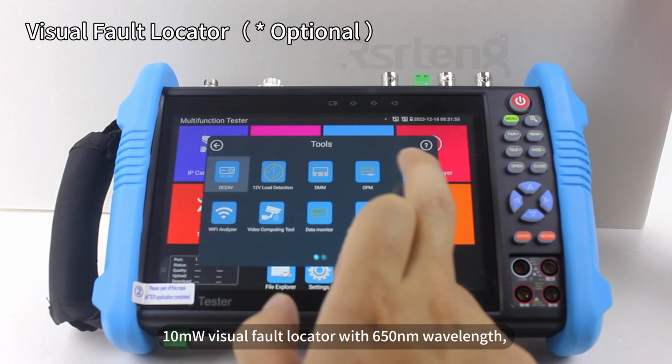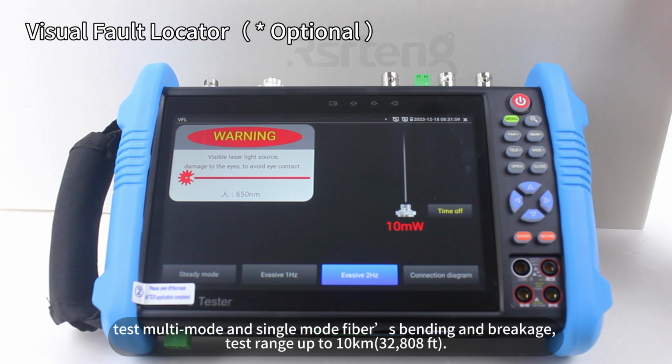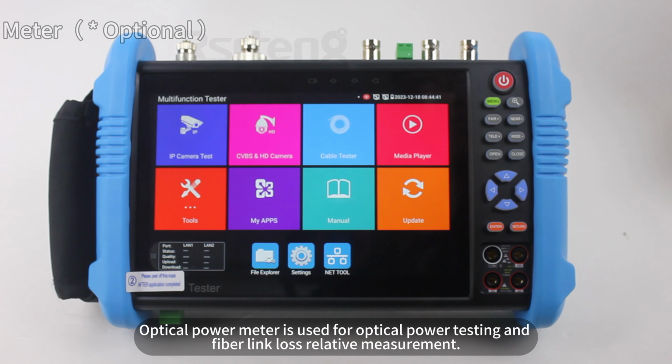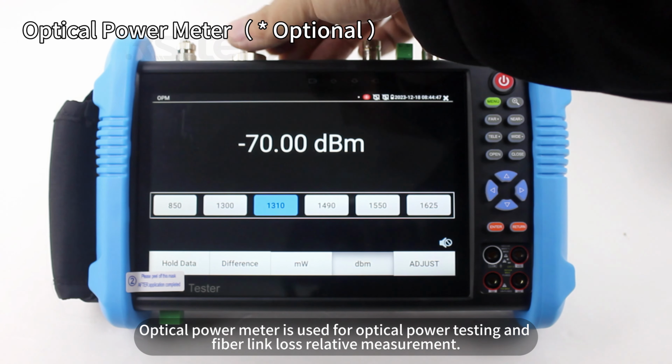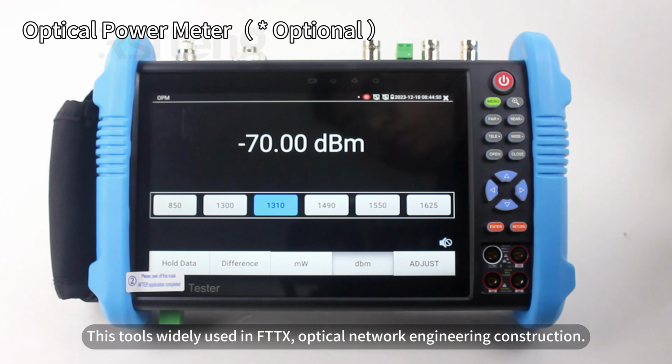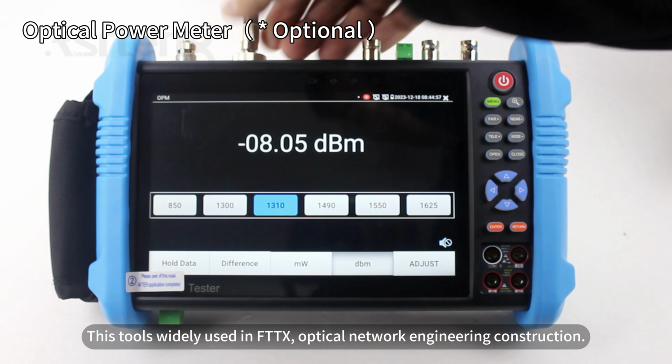10 mW visual fault locator with 650 nm wavelength. Tests multi-mode and single-mode fiber bending and breakage. Test range up to 10 km, about 32,808 feet. The optical power meter is used for optical power testing and fiber link loss relative measurements. These tools are widely used in FTTx optical network engineering construction.